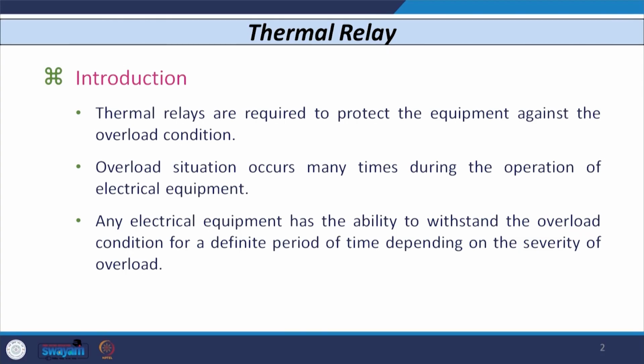If we want to detect the overload condition in the equipment, then thermal relays are widely used. The overload situation occurs many times when the equipment draws current more than the rated value. Any equipment is capable of withstanding the overload condition for a certain definite period of time, and this time depends on how much overload is carried by the equipment. The higher the overload, the less is the time up to which the equipment can withstand that overload condition. The less the overload, the higher is the period of time up to which the equipment can withstand it.